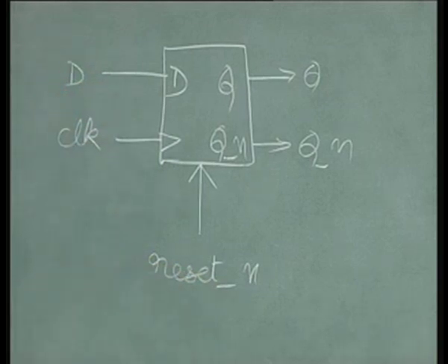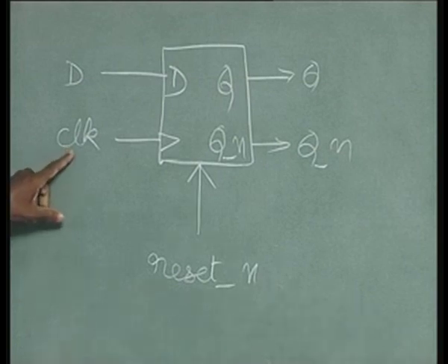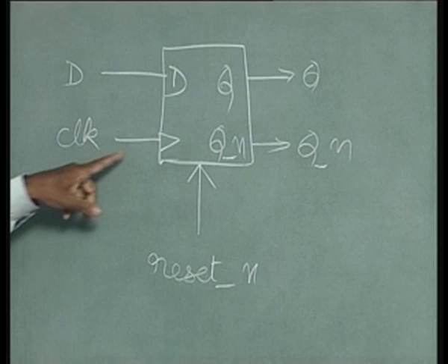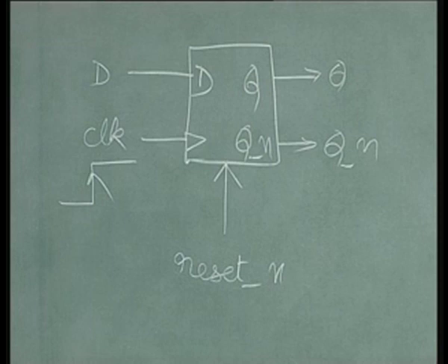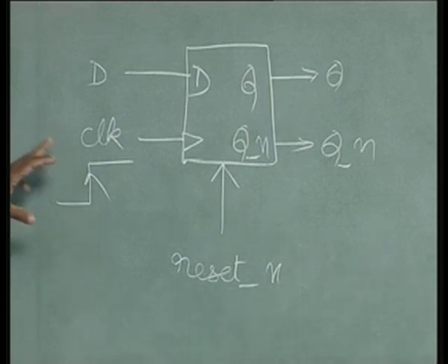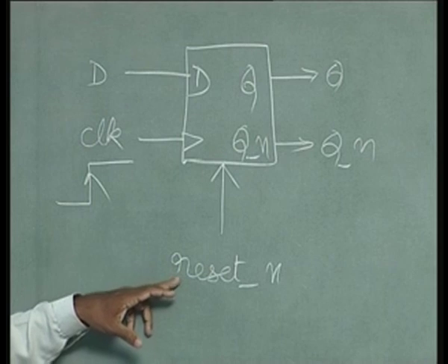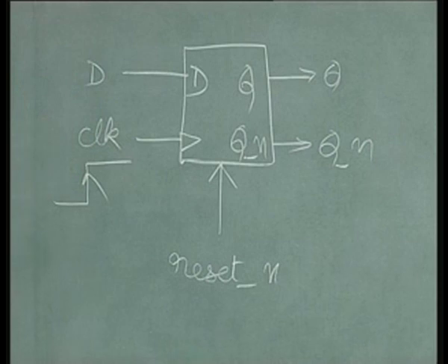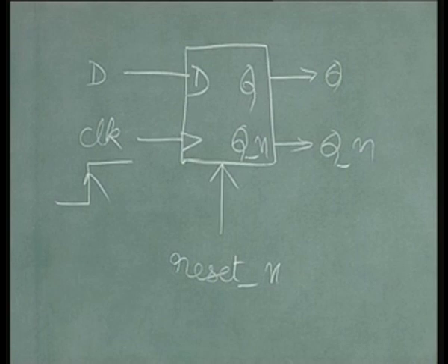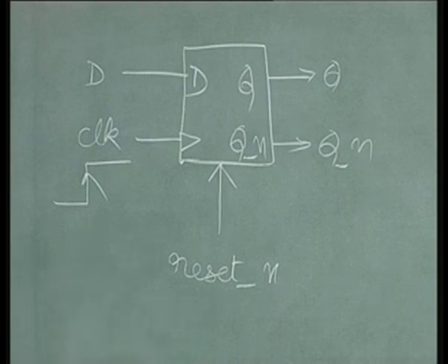And another thing that we have seen here is a clock input. You have already seen that it signifies a positive edge clock. And once again this positive edge of clock and asynchronous reset active low are very popular among designers, especially in the United States, and we adopt this throughout our course. And now it's very easy to code this. What we want is, we'll reuse the same always block, but the connotation is different here because this is a sequential circuit.